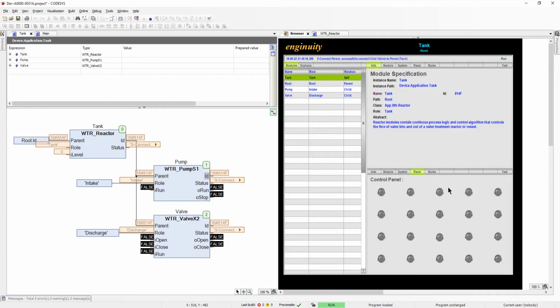On the native HMI, the screens that are used in the frame have to be selected beforehand. They're assigned an ID number, and then the way you select the frame to be displayed is by the ID number. On Ignition and other external HMIs, the way you specify what screen is to be displayed inside the frame is by name.